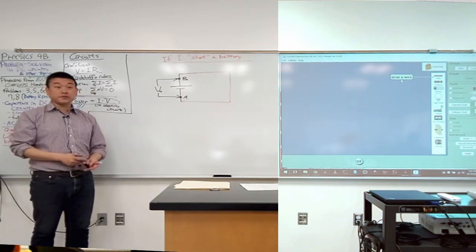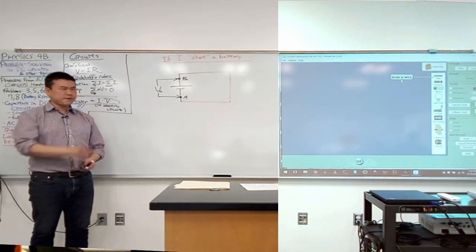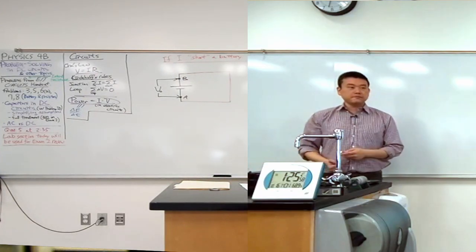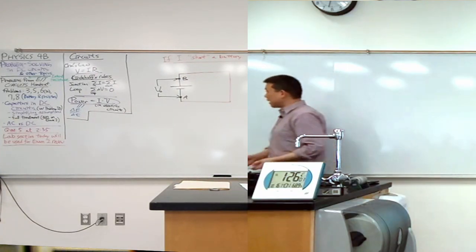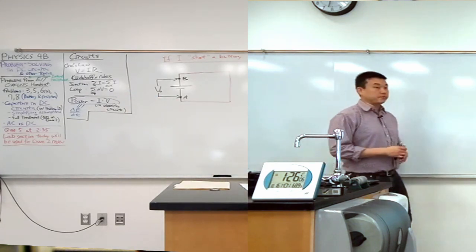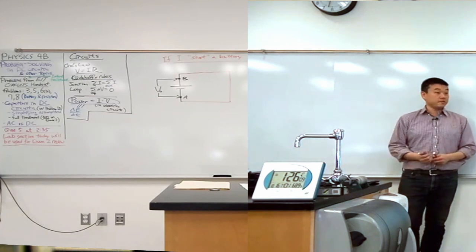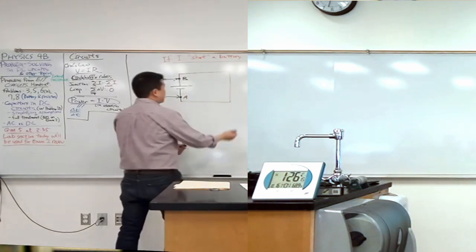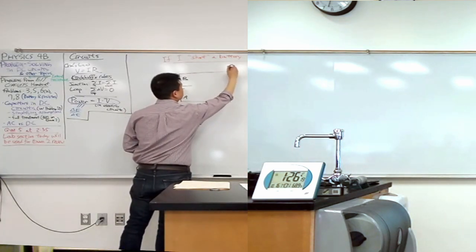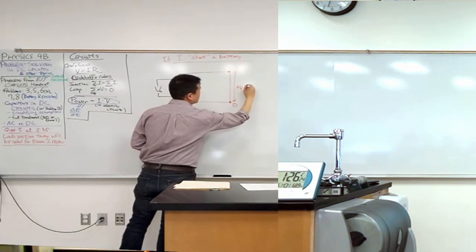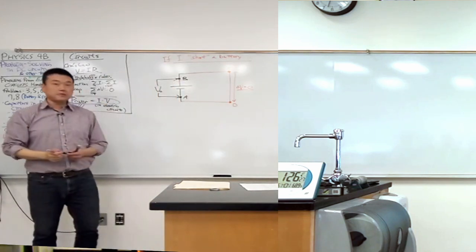that you also use when you're solving circuits? Someone from maybe this side of the class. It's a conductor, so that's what it's made out of. But when you're trying to analyze a circuit using Kirchhoff's rules, what's the one property about the wire that you need to use over and over? Voltage is constant throughout the whole wire. In other words, if you take these two points, points C and D, I know the voltage difference between these two is equal to 0 because it's connected by wire.